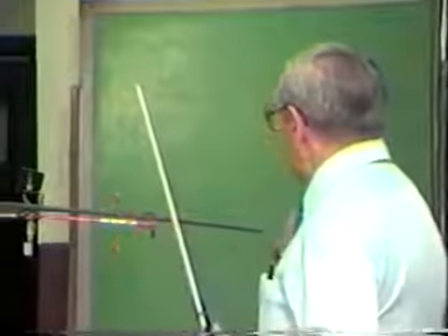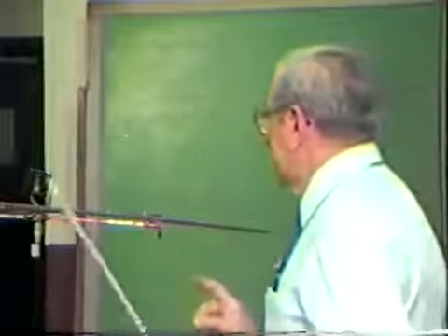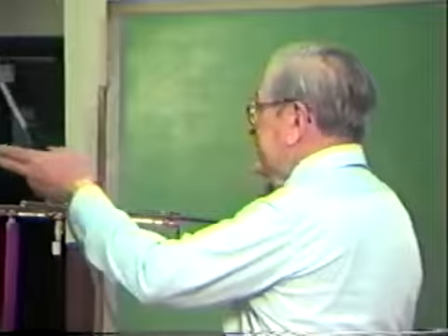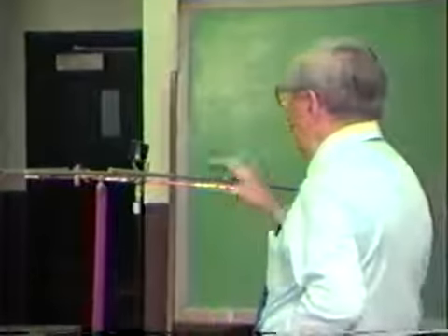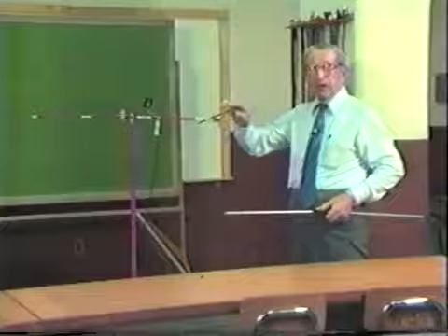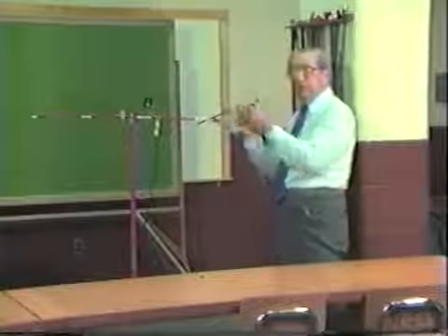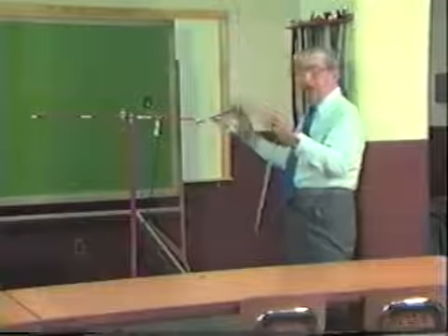The reflector is 5% longer than the driven element. What happens is the radio frequency waves are building up and collapsing on this element at 146 million times per second. When you put a longer element here, it takes a little bit longer time for the RF to bounce back and forth on the element. Difficult to comprehend, but understand it.